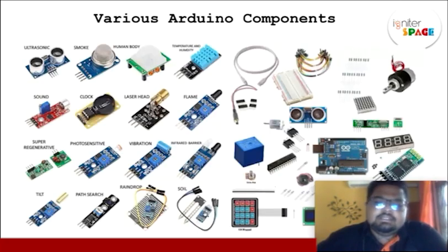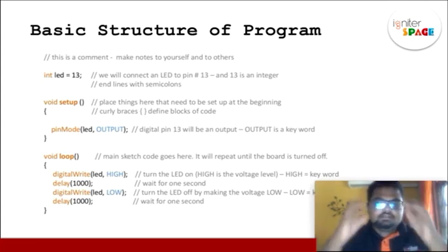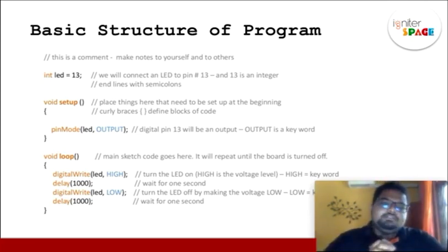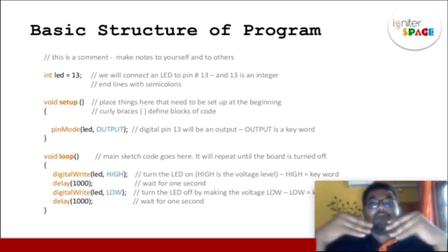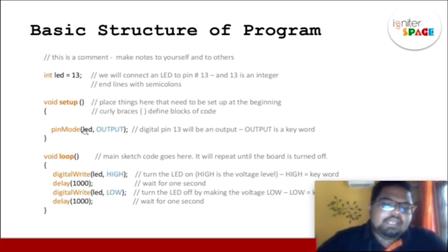So here what we actually do is, I said these pins can be both input and output. So we need to declare if we are taking an output from this pin, or we are giving an input electric signal. For an LED, what do we generally need? Do we need to input something or output? Alright, we need to output an electric signal and make it work, right? So that's why we have declared this LED as an output pin. And so that's what we are doing.